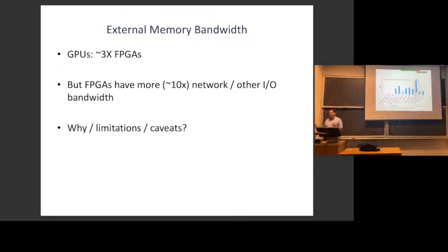But a typical big FPGA could actually talk to about 6 different DDR channels. So they could take these same chips, and if they made their own board, they could have higher bandwidth to memory. Part of it is that, but they are also correct that with most accelerator boards, you just go buy a board that somebody else made, and they usually only hook up a couple of DDR channels to the FPGA. That's a decision board manufacturers make, whereas GPUs hook every pin they possibly can up to graphics DDR. So if you choose to, at board design time, you can increase this external memory bandwidth on an FPGA.